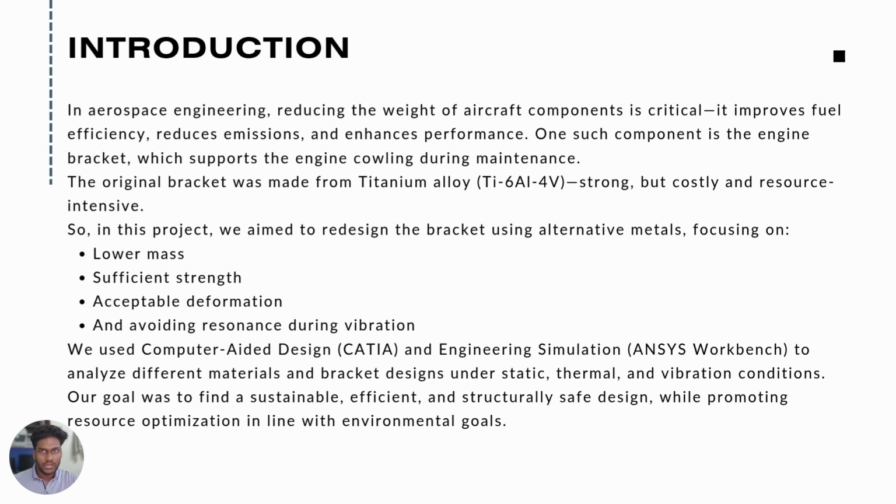In aerospace engineering, reducing the weight of aircraft components is critical. It improves fuel efficiency, reduces emissions, and enhances performance. One such component is the engine bracket, which supports the engine cooling during maintenance. In this project, we aim to redesign the bracket using alternative methods, focusing on reducing the mass, with sufficient strength, less deformation, and avoiding resonance vibration.